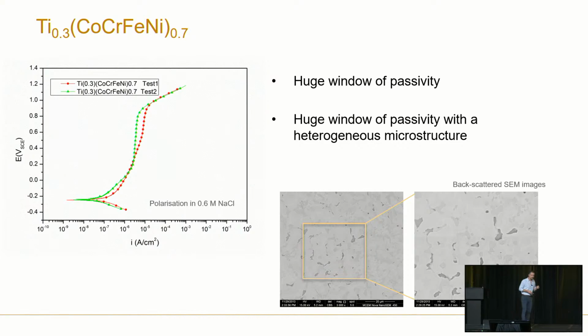All right, so this was really, really interesting. If there's corrosion people out there, you'll probably say, holy moly. Typically, when you see a lot of passivity in our world, you normally have very uniform microstructures. Microstructural heterogeneity is usually a killer for corrosion because you normally get microgalvanic cells forming, you get localization of anodic reactions, cathodic reactions, really bad things.